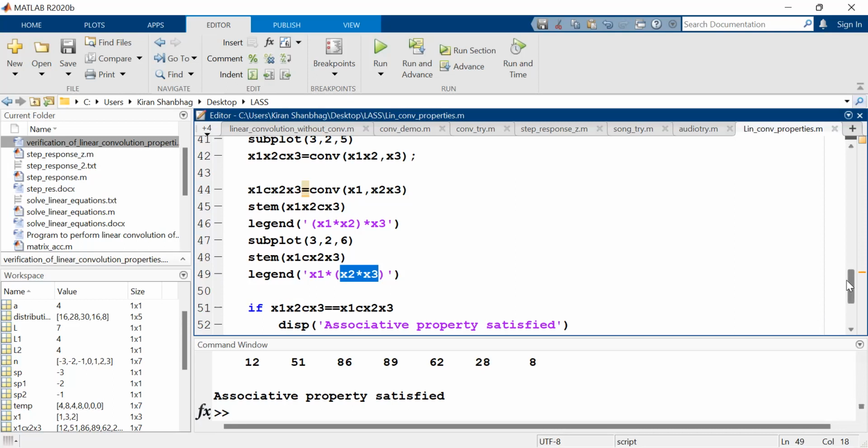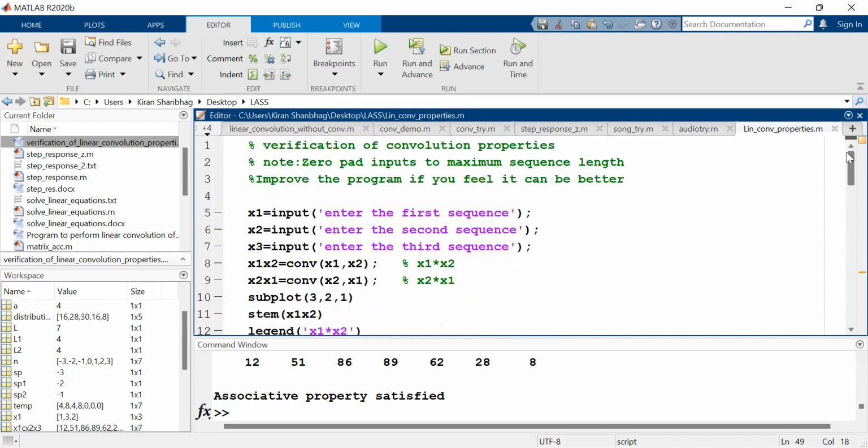So we are happy that convolution is satisfying these properties. Which ones? The commutative, that means the interchange does not make any difference. Second is the distributive, that means individual impulse responses can be added, then you convolve. It's going to give the same result, which computationally can be very, very efficient. You can reduce the number of multiplications.